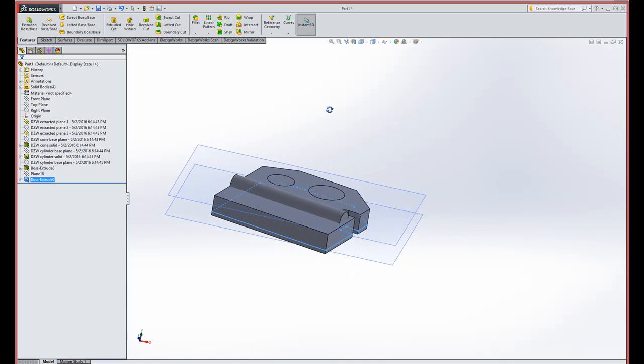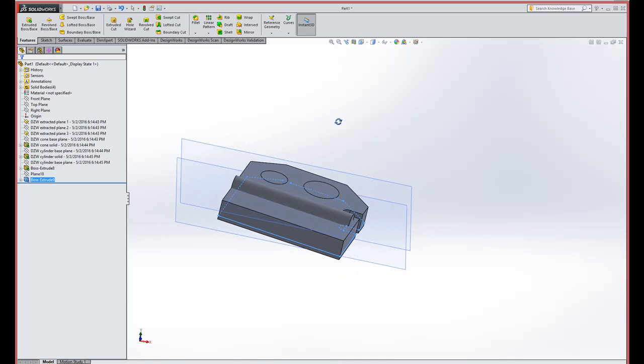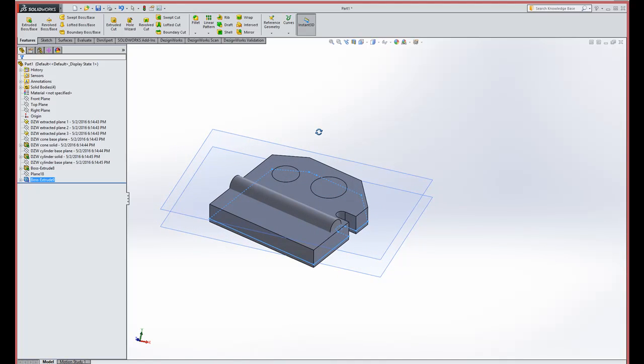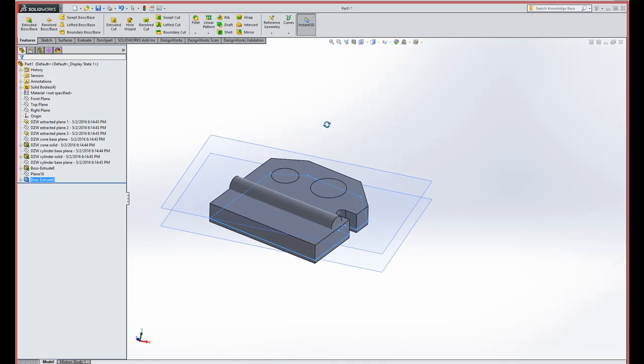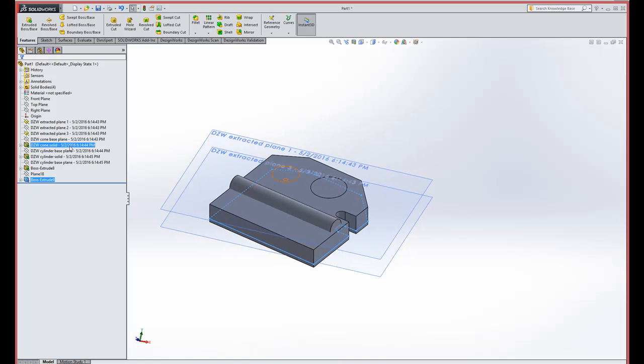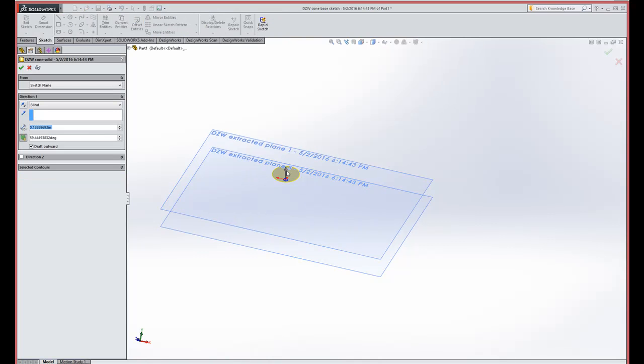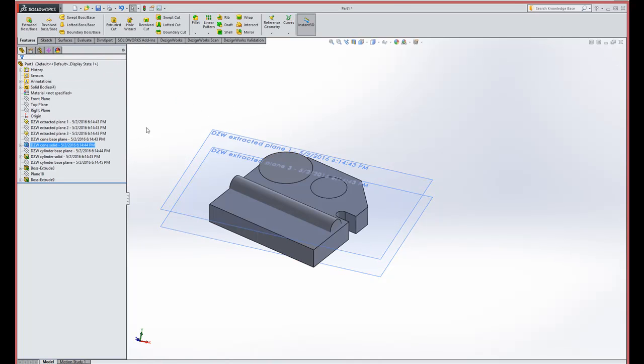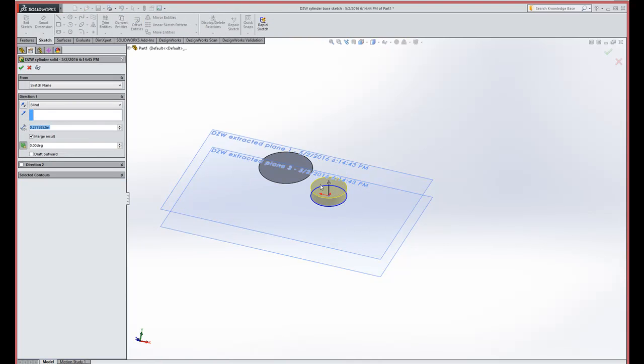From this point, we can go ahead and actually finish cutting things off. There's a plane that needs cut off. Notice these features here are nearly flush. Let's go ahead and pull those up a little bit. Notice they appear right in the tree. You say edit feature, and all the information's there. I'm going to pull them up just a little bit so it's above it, because we're going to use the combine tool. Pull that up just a little bit because it's flush.